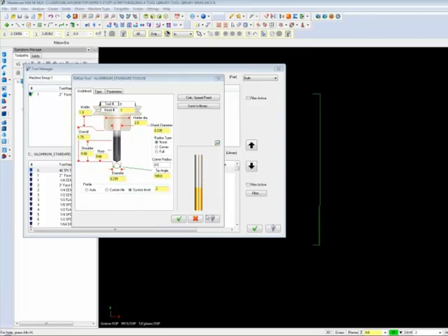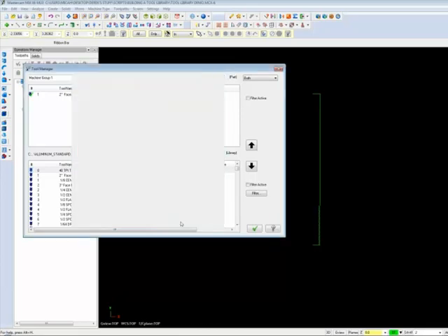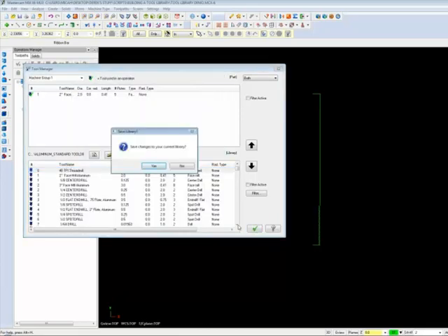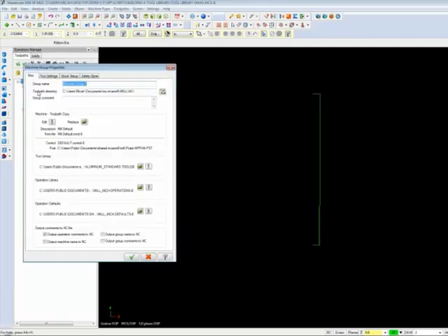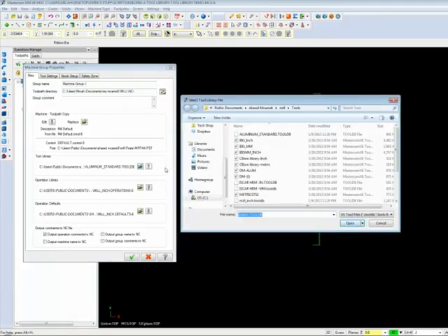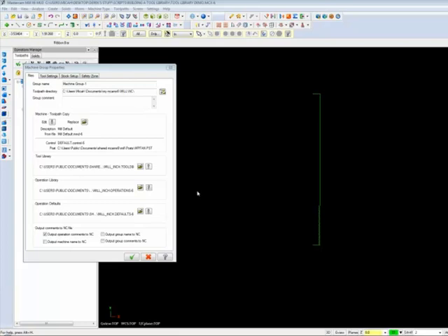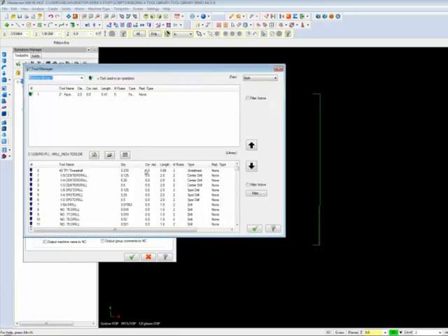To see if the new tool is in the new library, exit the Tool Manager, click on the Files tab under Machine Setup. Change tool libraries using the Open File button. We drop that into our mill-inch library. Then click the exclamation point to open up the Tool Manager. Since the tool is tool number 0, it's the first tool in the list. When importing tools from other libraries, remember to change any necessary parameters, such as feeds, speeds, or coolant settings.